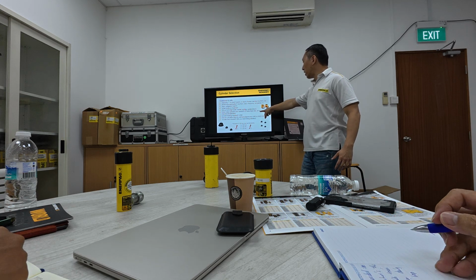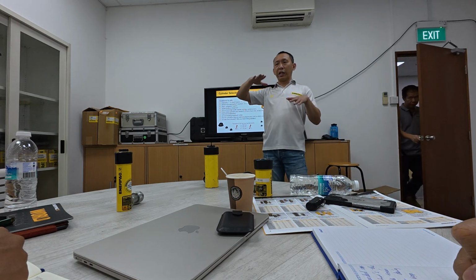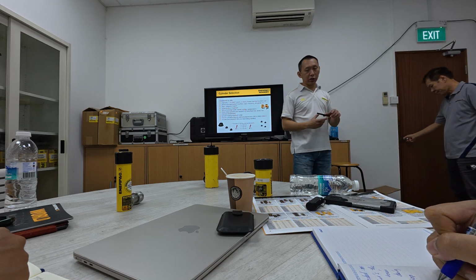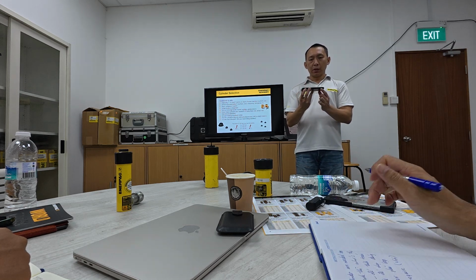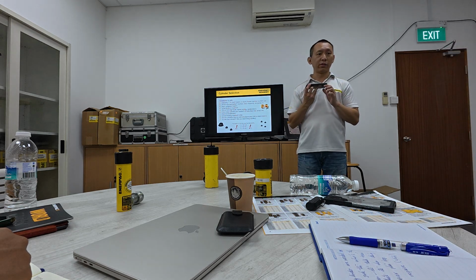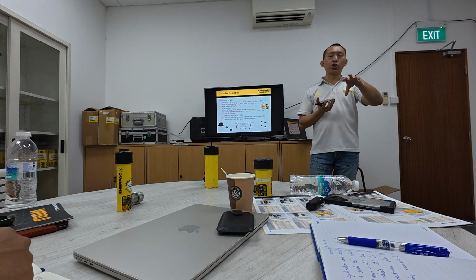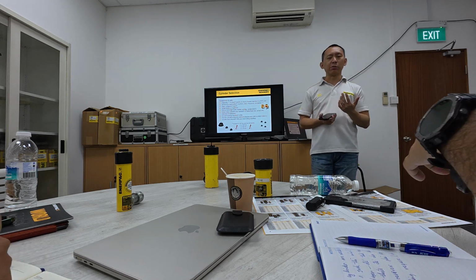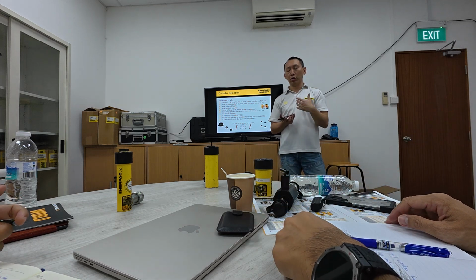Does the cylinder have to work simultaneously? What do you mean by that? It means when lifting, does that need to be even? Just now, when I mentioned the lifting, for the load we always assume that it's evenly distributed. This is the V66 load holding valve. We usually assemble it to the cylinder side. It depends on how the customer wants to use it, but usually at either the cylinder side or the pump side,